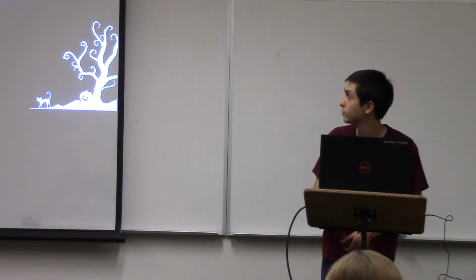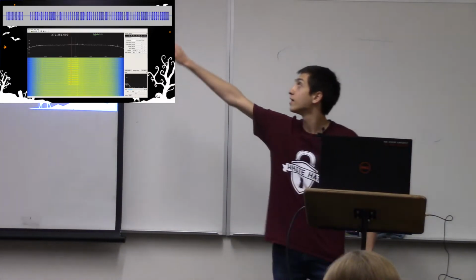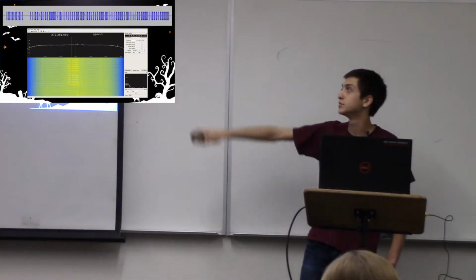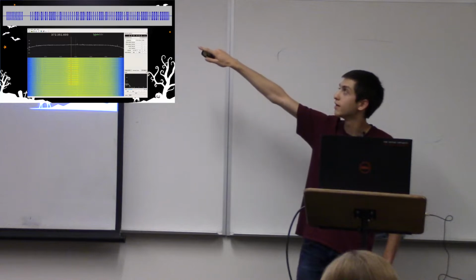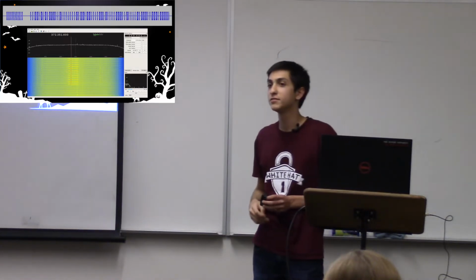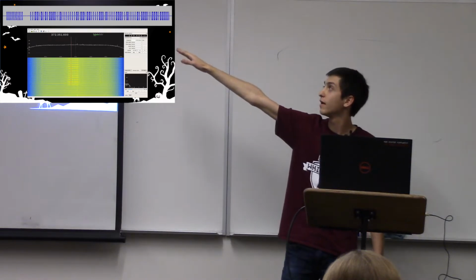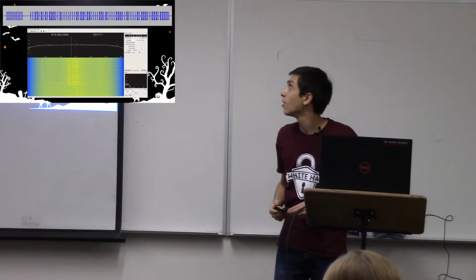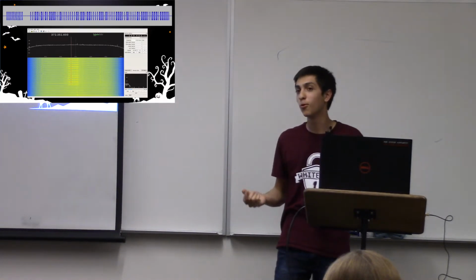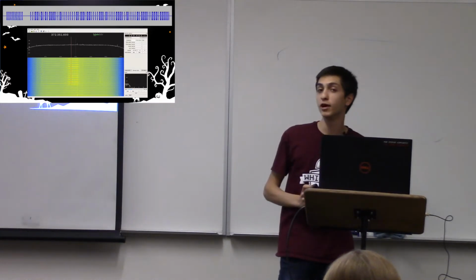Well, I went ahead and did that beforehand. And I got that signal up there. And that looks very similar to the FCC report, where it just does a bunch of junk in the beginning, there's a break, and then does some other junk. But if we take a look at the widths of those waves, in the beginning, those are all equal length widths. And then there's a break, and then the widths start to vary. Now, it seems like there's about two widths. There's a short one and then a long one, or 1 and 0, binary. So it looks like it's sending some kind of binary.